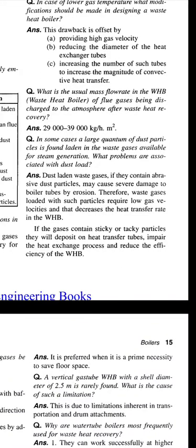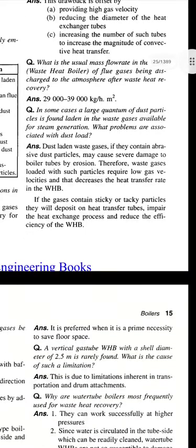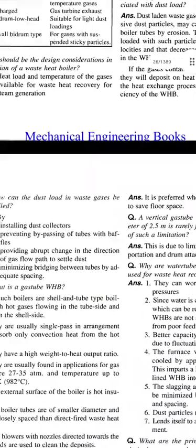Therefore, waste heat gas loaded with such particles requires low gas velocities and that decreases the heat transfer rate in the waste heat boiler. If the gases contain sticky or tacky particles, they will deposit on heat transfer tubes, impair the heat exchange process and reduce the efficiency of the waste heat boiler.